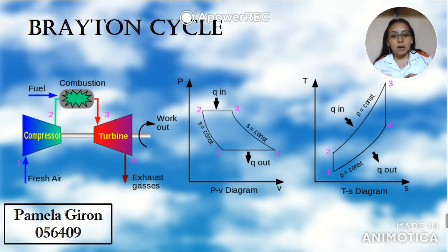In fact, there are gas turbine engines in which the fluid effectively recirculates and only the heat is transferred to the environment. For these engines, the ideal Brayton cycle model is more approximate than for open cycle ones.